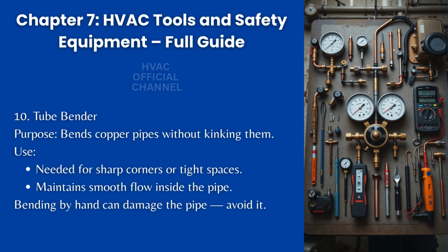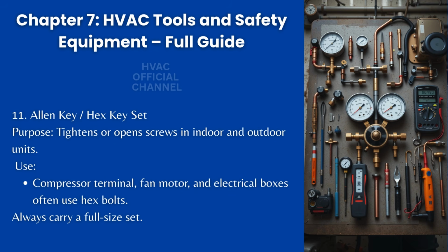10. Tube bender. Purpose: bends copper pipes without kinking them. Use: needed for sharp corners or tight spaces. Maintains smooth flow inside the pipe. Bending by hand can damage the pipe. Avoid it.